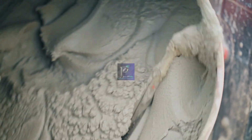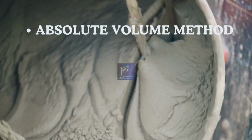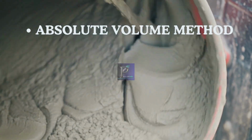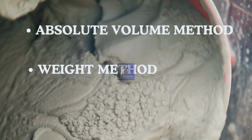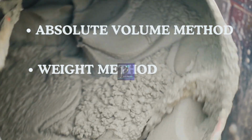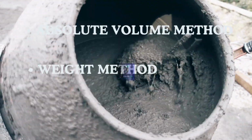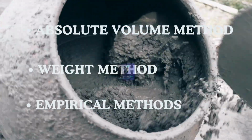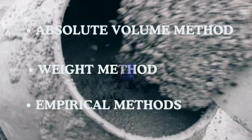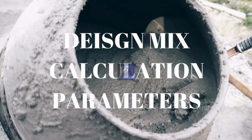There are several established methods for designing concrete mixes that include the absolute volume method, a detailed calculation that determines the volume of each ingredient required to achieve the desired properties. Weight method. This method involves calculating the weight proportions of each component based on the desired concrete volume. Empirical methods. These methods use established guidelines and past experience to estimate mix proportions. Mix proportion calculation. What are the parameters?